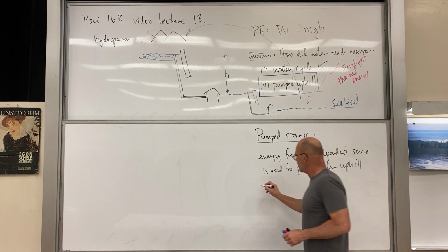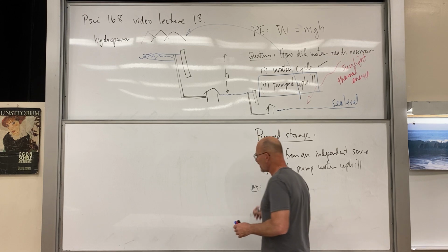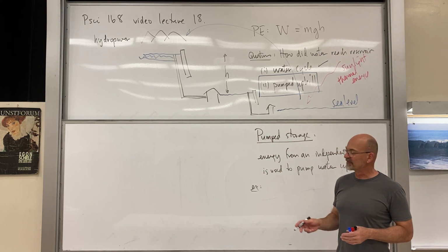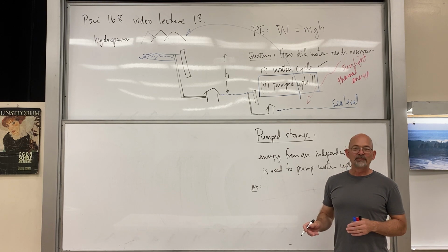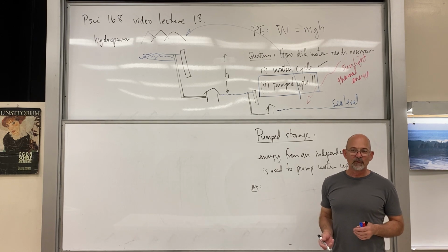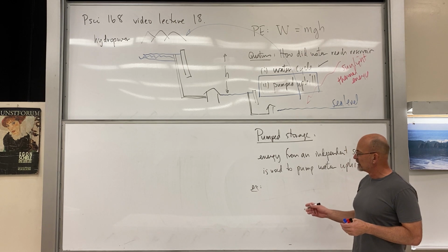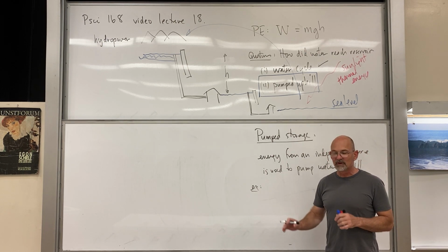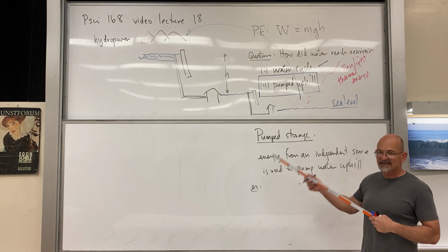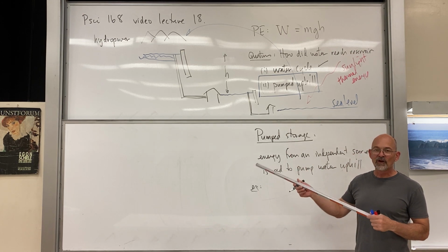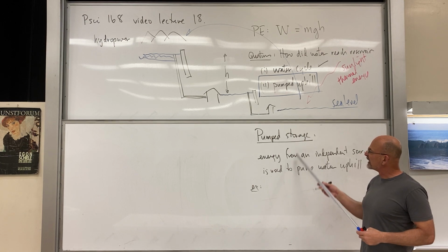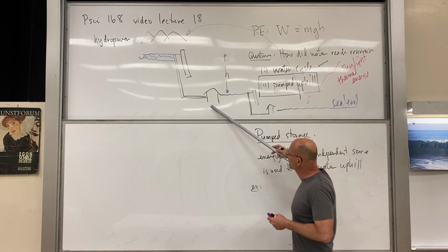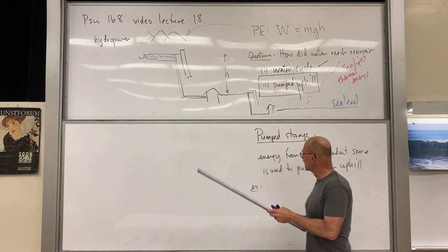For example, there could be some gas-fired, coal-fired power plants that can't just be shut off and turned on with the flick of a switch. These are major operations, so the operators want to keep them running as steadily as possible, and when they produce excess energy, when the demand is low for their production, they sell that to our power plant up here, who's going to use that excess energy to pump water up the hill.